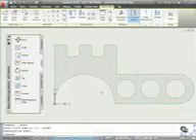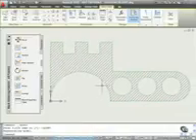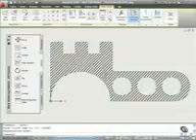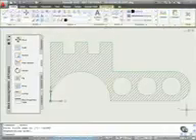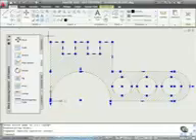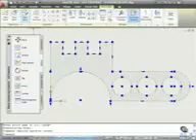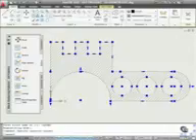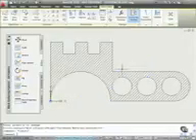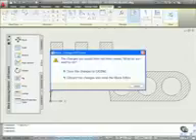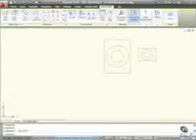Now look, you can see everything remains on its original layers, the green layer and the black hatch layer. Now, if I go to the Home tab, I can edit this and select everything, put it all on a 0 layer. So if I go Home now and go Layer and then 0, everything goes onto layer 0 in the block editor. So if I hit Escape now, that's all on layer 0. Now as soon as I go to Close, it'll say Save the changes to casing. So I'm going to save those changes.